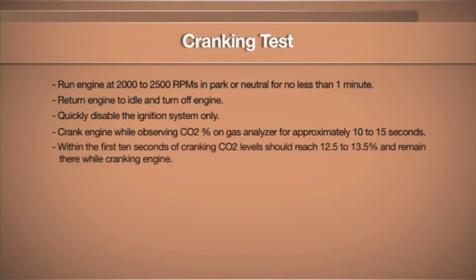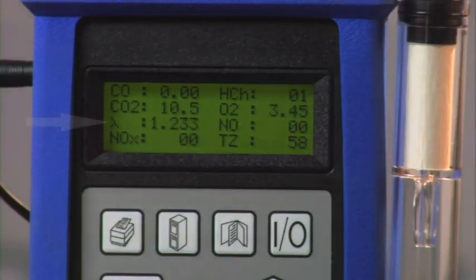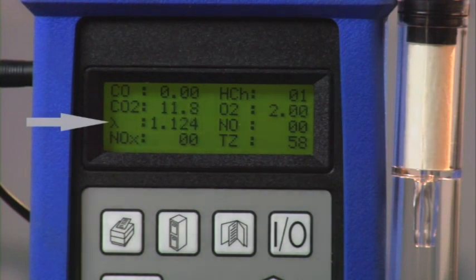When the CO2 levels climb above 12.5 to 13.5%, this gives us an indication that we're able to take HC and CO and oxidize them in that converter, turning it into CO2. We can see our levels reach 12.2, 13.6, and 13.7. We're up over the 13 range with this catalytic converter. We can see this catalytic converter is capable of oxidizing HC and CO into CO2.